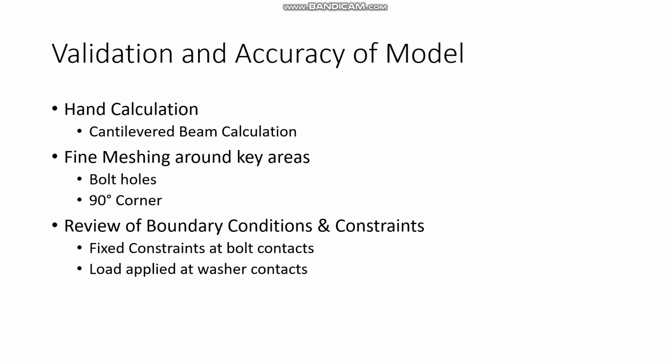And lastly, to provide a realistic model, the boundary conditions will be thoroughly considered. The way the bracket interacts with the loaded and mounting bolts must be accounted for as realistically as possible. So if the bolt contacts the bracket, the boundary conditions have to account for how that bracket and the bolt interact.